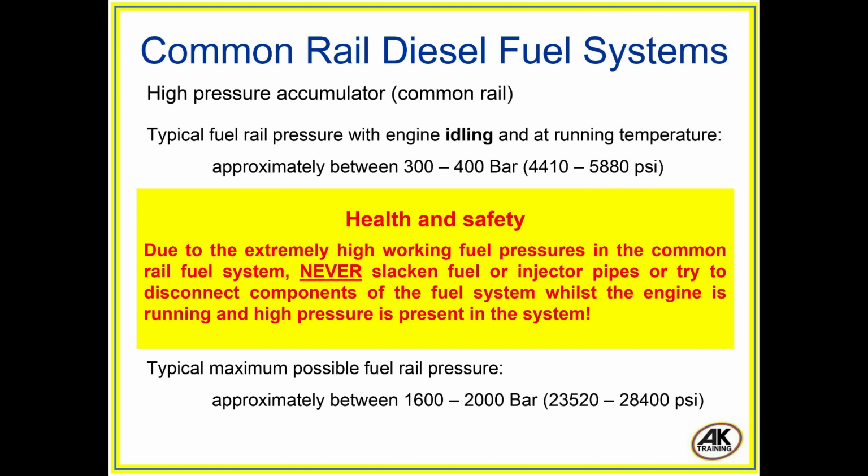Health and safety. Due to the extremely high working fuel pressures in the common rail fuel system, never slacken fuel or injector pipes or try to disconnect components of the fuel system whilst the engine is running and high pressure is present in the system.